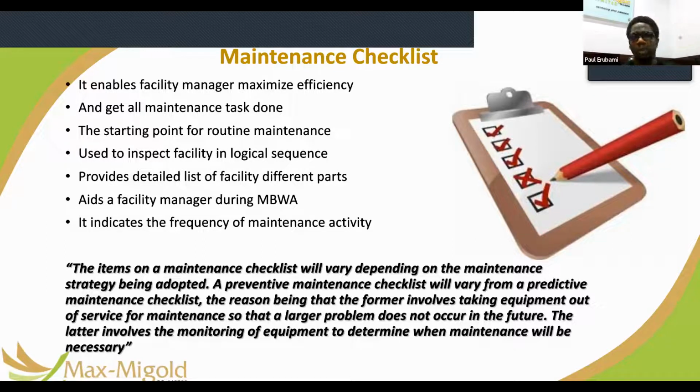Right, so back to that air conditioning example. I go into the indoor unit, I open it, take out the filter, step one, do that to the filter, clean it or wash it, and bring it back. I bring in a suction nozzle and suck the dirt out of the internal drain. I bring in a vacuum, I suck up all the dust in the evaporator, right? I put five steps already, okay?